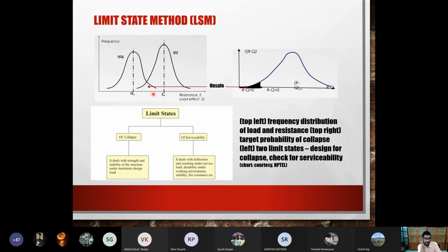I didn't hear you. Load, sir. Load. Why do you say that? Because sometimes there may be natural hazards or impact loads. Okay. Yeah, one of the reasons is those natural hazards, and even without natural hazards, if there's a building, somebody changes the use of the building, load will change. For example, these days a lot of the old cinema theaters, people change to marriage halls. So change of application, change of use, relates to a change of load also. Okay, so those kind of things as well. So load is more uncertain.